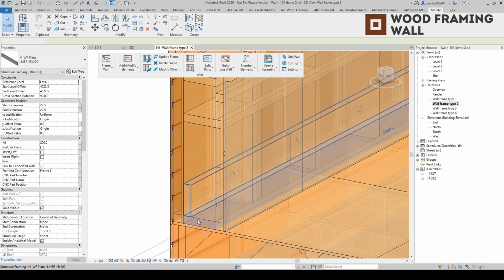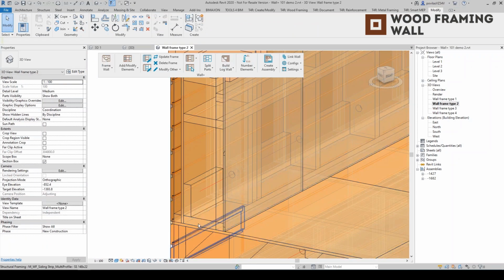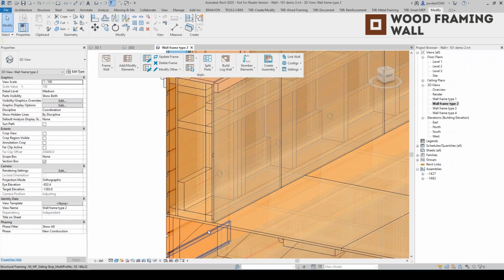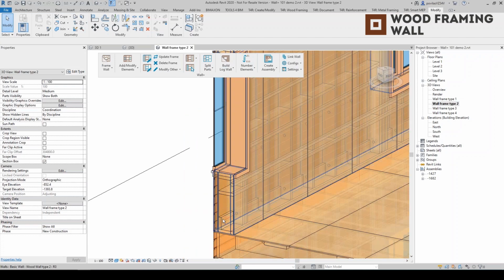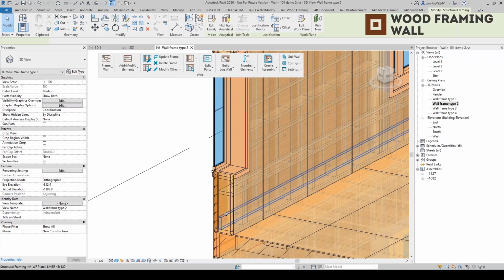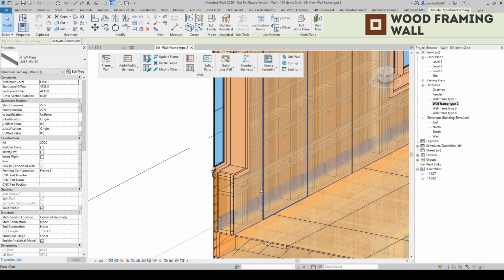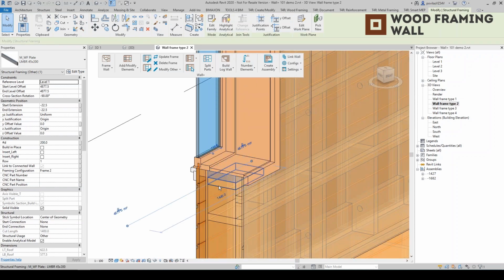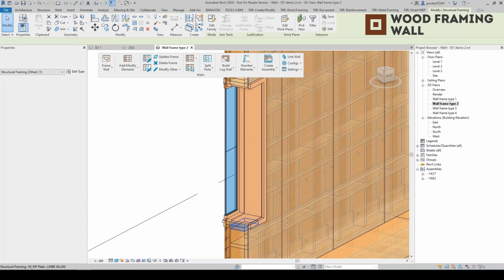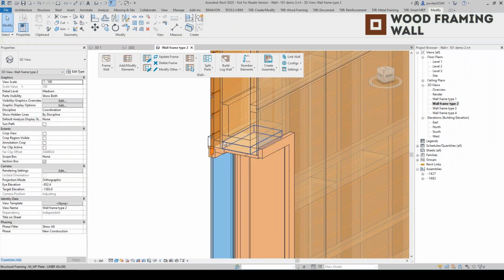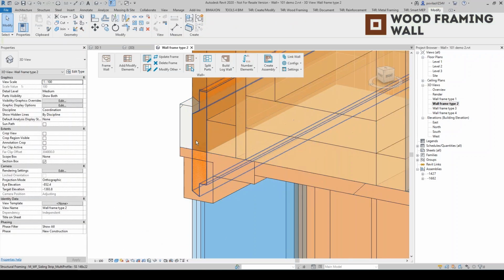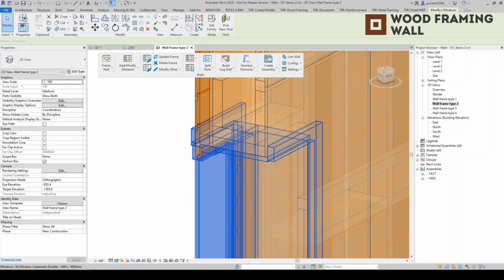Okay, so the base plate in this case does something else. We have a single plate that just lays on the prefabricated floor panel, for example, and then just another plate that's turned 90 degrees, and then two bottom sill plates, okay, top plates, okay.